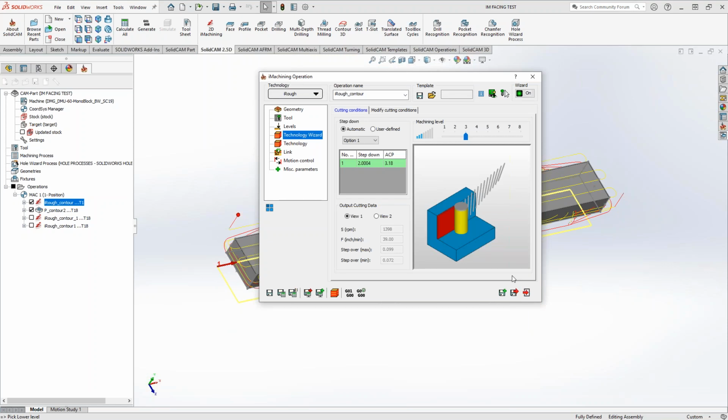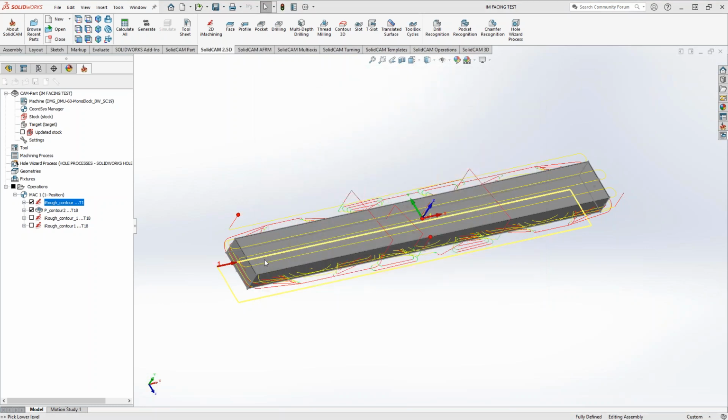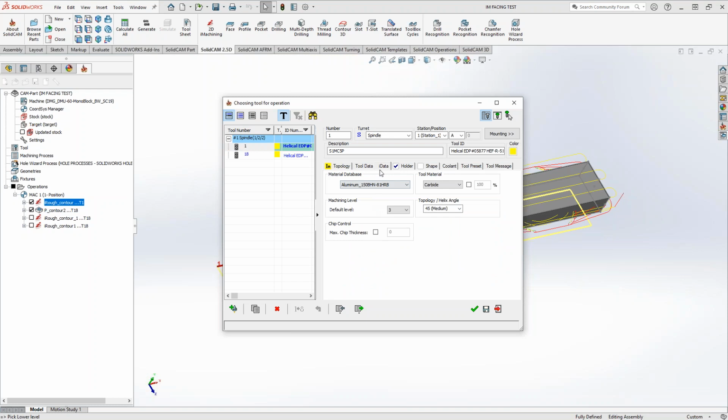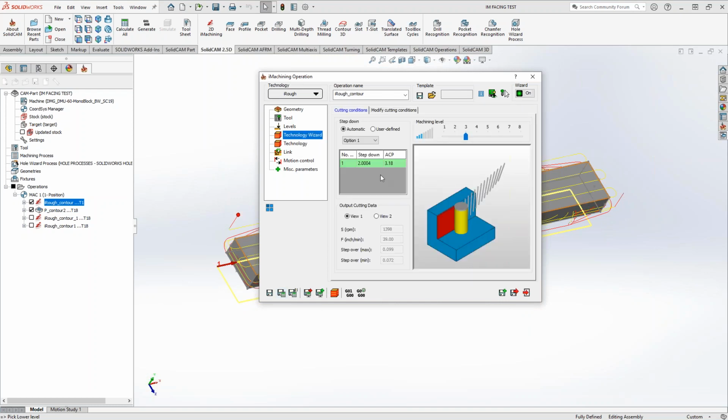Oh, there we go. Okay. So I looked away for a second. I didn't see what you changed. I had too many flutes in there, so I switched it over to a 5 flute, which would be a normal end mill, and then put in our data with a 45-degree helix angle. So if we were actually to cut this part, and we had a 1 inch deep pocket, that's telling us this 1 inch tool with the 45-degree helix and 5 flutes is going to be the perfect tool for that job. And it's telling us right there.